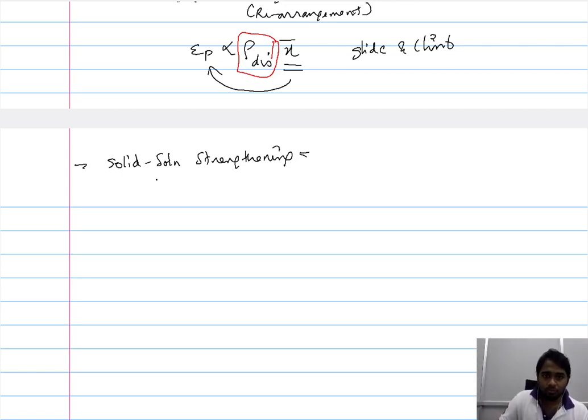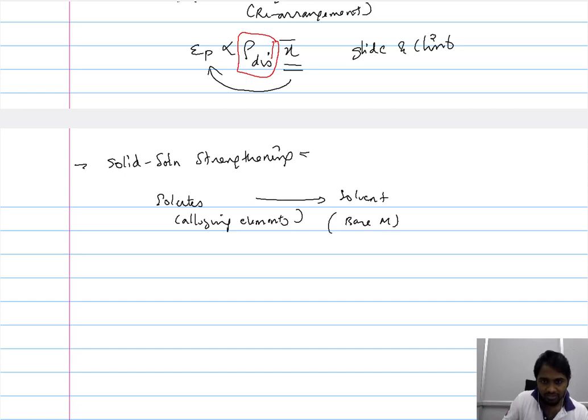So we want to enhance the life of the creep material by reducing the creep rate in the steady state condition. One way of doing that is reducing the rate at which the dislocation propagates, or impeding the proper path of the dislocation. Now we want to do that by introducing some solutes, that is nothing but the alloying elements. You want to introduce that to the solvent, that is the base metal. So by introducing this, we want to impede the propagation of the dislocations.